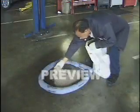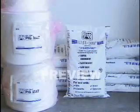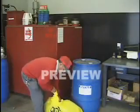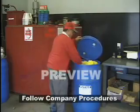Specially developed absorbent materials are available for spill cleanup. These products are offered in pillows, pads, sheets, tubes, and other shapes to fit all cleanup needs. Once the absorbent material is saturated, it should be placed in a large disposal drum and sealed with a drum cover.